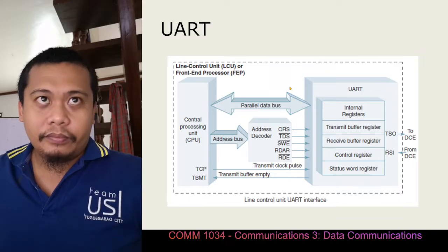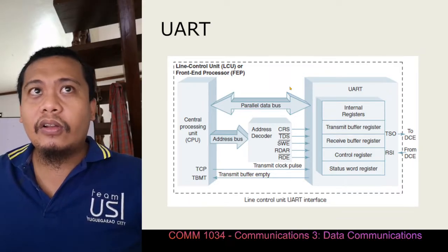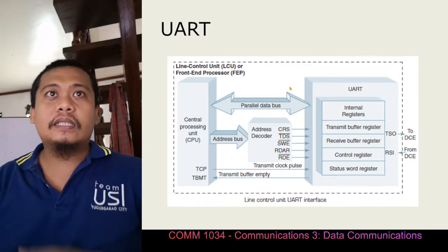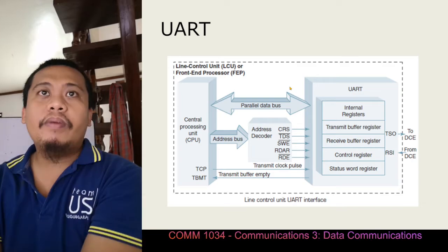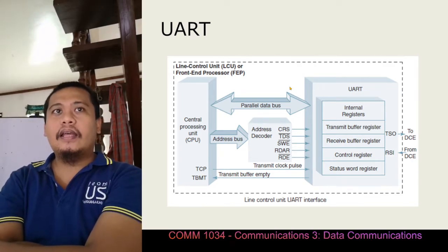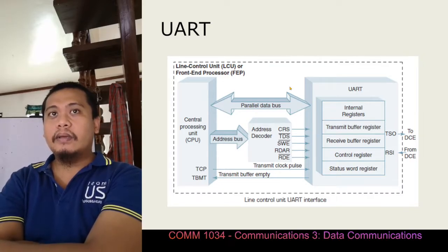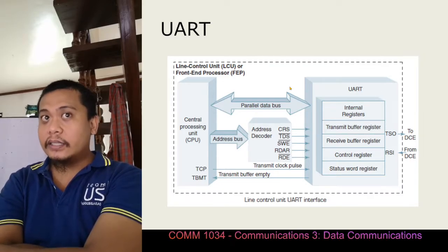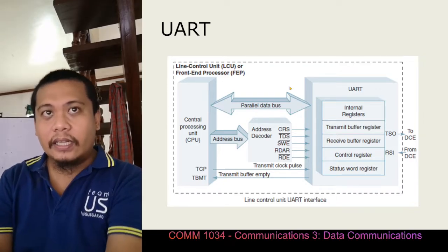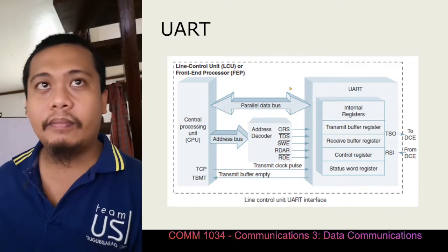The CPU coordinates data transfer between the line control unit and the modem. The CPU is responsible for programming UART's control register, reading the UART status register, transferring parallel data to and from the UART transmit and receive buffer registers, providing clocking information to the UART, and facilitating the transfer of serial data between the UART and the modem.